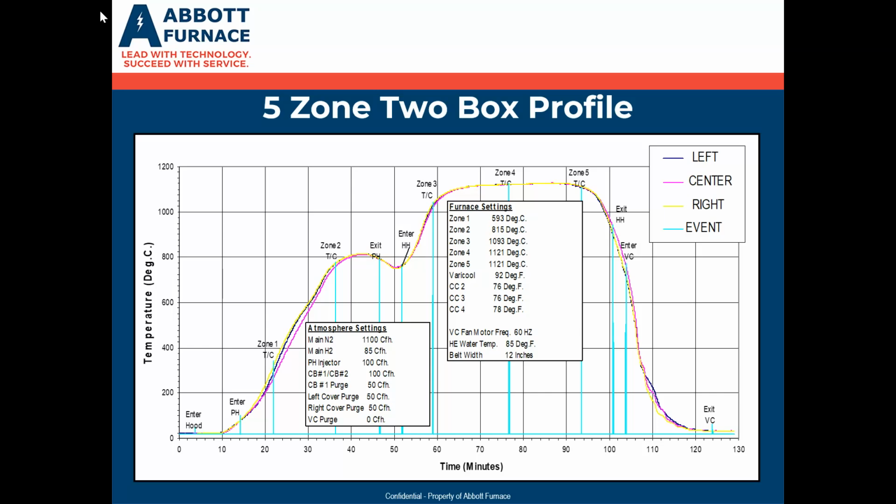And you measure down to your preheat, exit your preheat box, and enter your high heat box. So those measurements are all taped onto our thermocouple. And then as it's going through, we hit an event button that gives us that mark on there, so we know where the tip of the thermocouple is as it's going through the furnace.